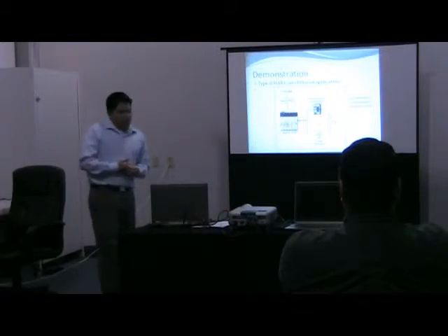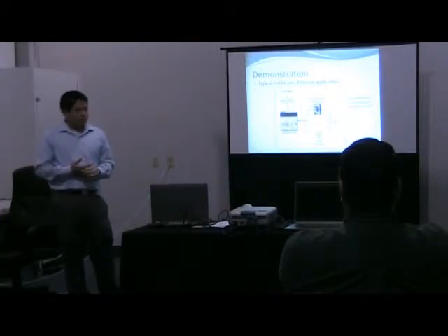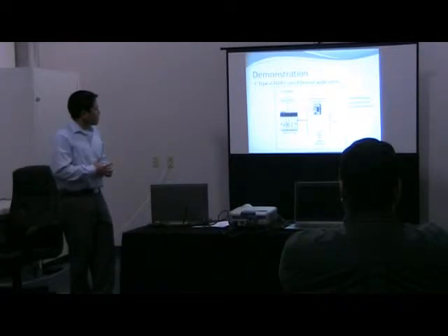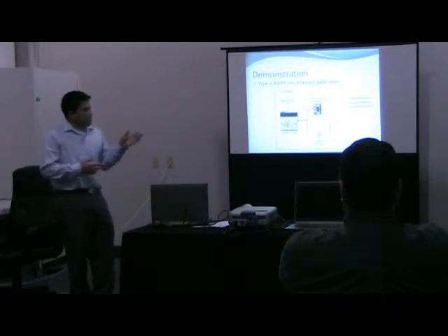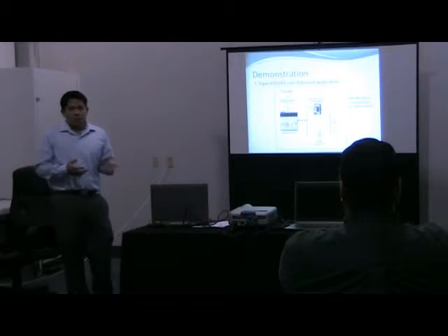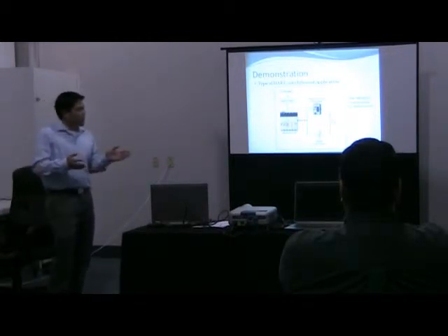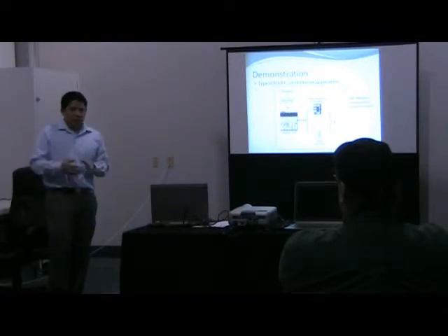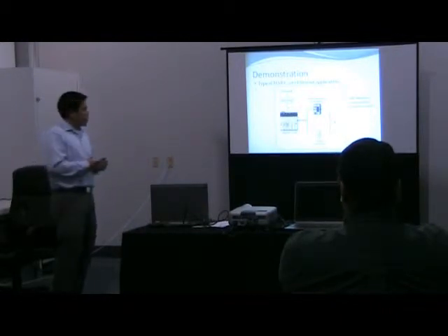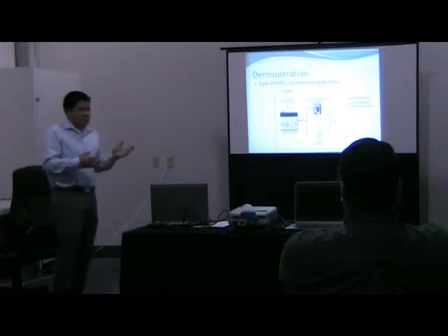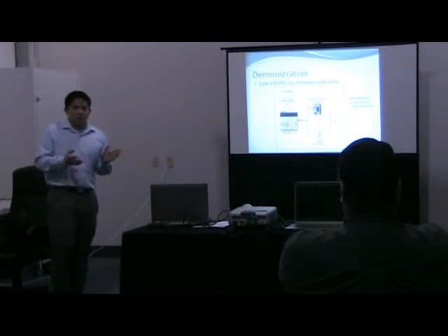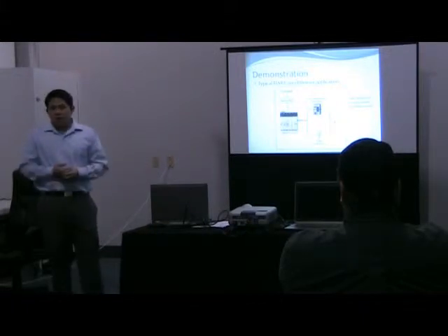Okay, so we now have our HART data going to SCADA, but there may be some common concerns with a configuration such as this. Maybe in a greenfield site, where you have a new installation or a brand new plant, this may be okay. But can you think of any pushbacks or concerns your instrument techs may have with this type of installation? Like a point of failure, maybe?